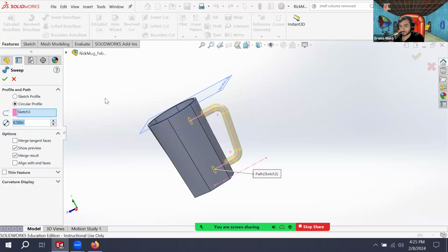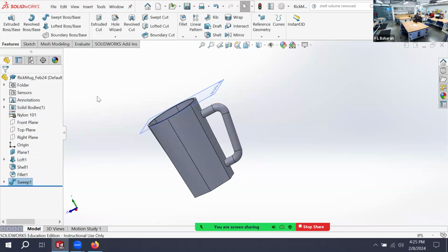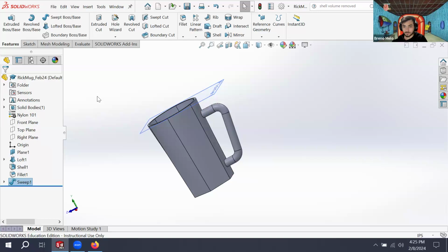Yeah, the sketch of my handle is still underdefined. Okay, so if your sketch is still underdefined, click on it and see how you can move it around. How does it move when you do that? It moves to the side. Then you need to put a dimension like I had on mine.